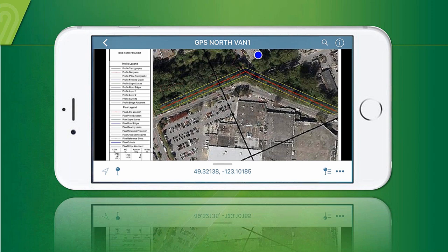And just a follow-up question on that one. Very much like I needed to do with live maps, you would need to have your design geo-referenced in order for this to work. Otherwise, it's not going to actually know where your PDF map is. So again, going up into the terrain setup tab, you would need to do that on the terrain side, making sure you've got a projection set up for your design, and we can export it over to Avenza.